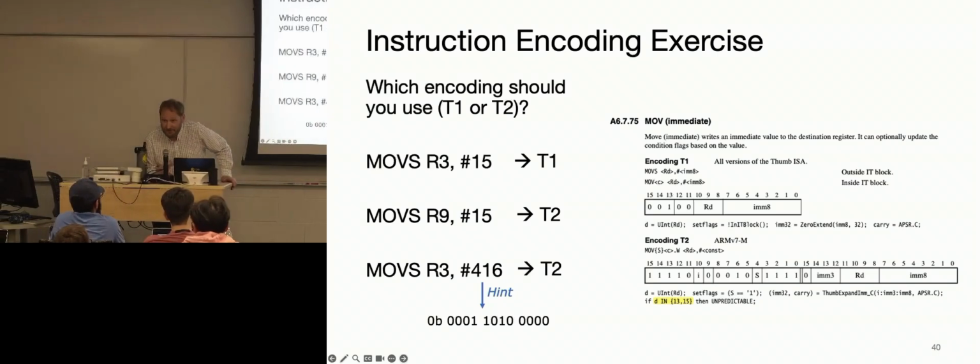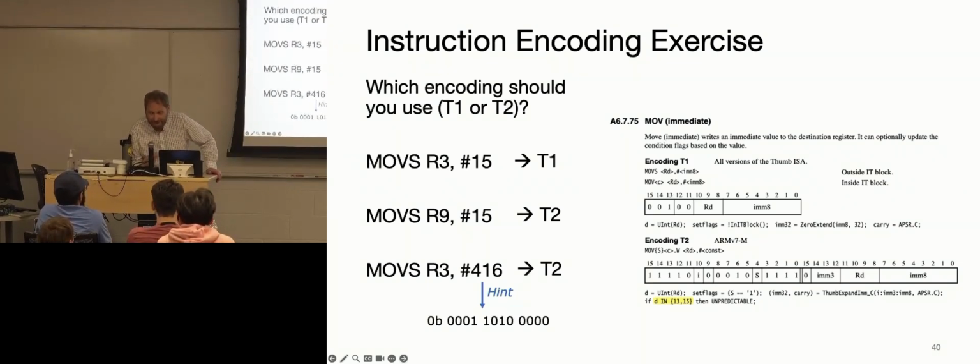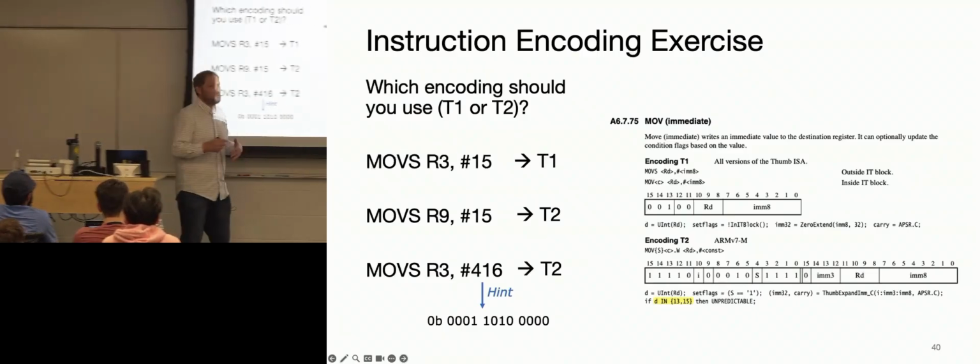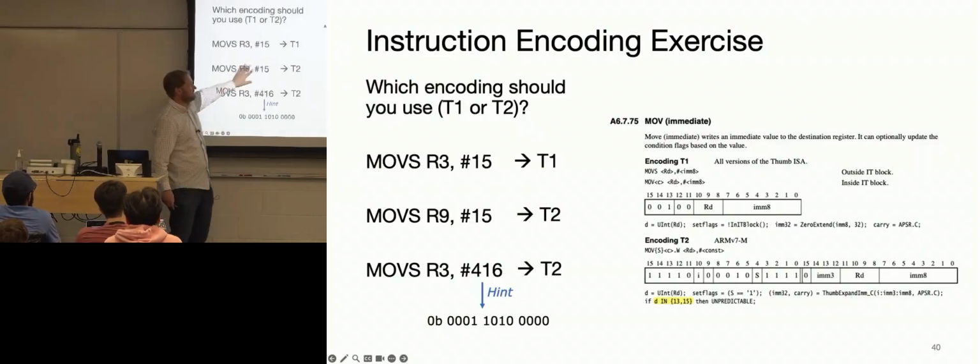So if it did a 16-bit instruction, and right after that it needed to do a 32-bit instruction, would it fill in the 16-bit instruction and do nothing, or would it just convert the 16-bit to a 32-bit instruction? Your compiler will always try to get you in 16-bit instructions if the encoding can be done that way.